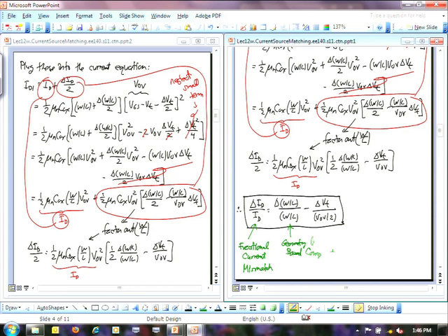I might end up with 0.7 volts. And so it's 0.7 minus 0.8 or 0.8 minus 0.7. So it can be negative or positive, and you have no control over what it is. Okay? So this is just one of the things that you worry about as an analog designer, especially as you go to these new technologies where the W over Ls are so small, right? The channel lengths now 34 nanometers, getting smaller, that sort of thing.